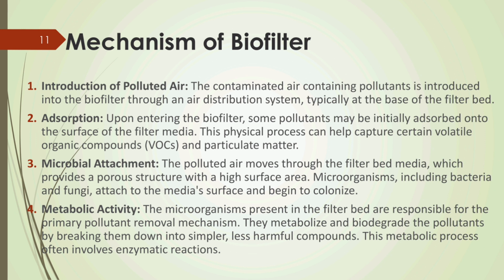Third is microbial attachment. The polluted air moves through the filter bed media, which provides a porous structure with a high surface area. Microorganisms including bacteria and fungi attach to the media surface and begin to colonize. Fourth is metabolic activity. The microorganisms present in the filter bed are responsible for the primary pollutant removal mechanism. They metabolize and biodegrade the pollutants by breaking them down into simpler, less harmful compounds. This metabolic process often involves enzymatic reactions.